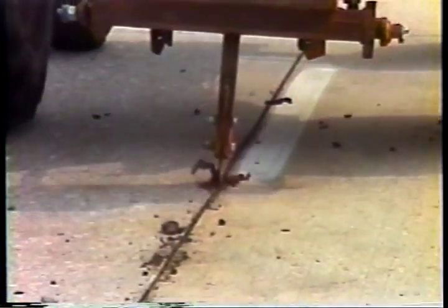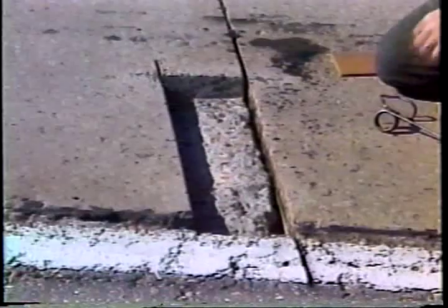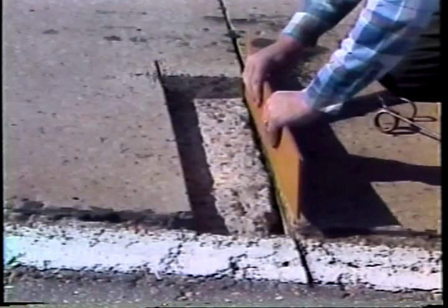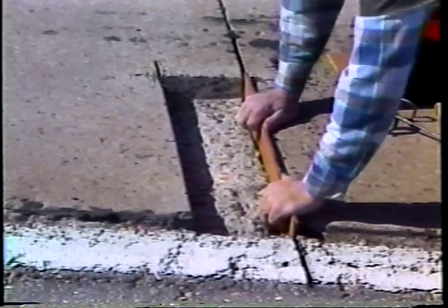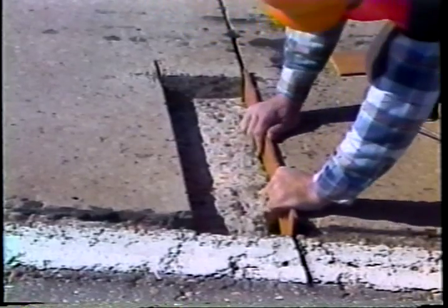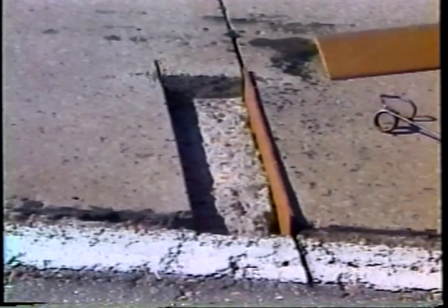The existing sealing material must be removed to prevent its contaminating the repair material. At both joints and cracks, a compressible insert is required. Its purpose is to prevent the repair concrete from intruding into the crack or joint. Now that's important because the forces created by expansion or differential movement of the adjacent slabs have to be reduced